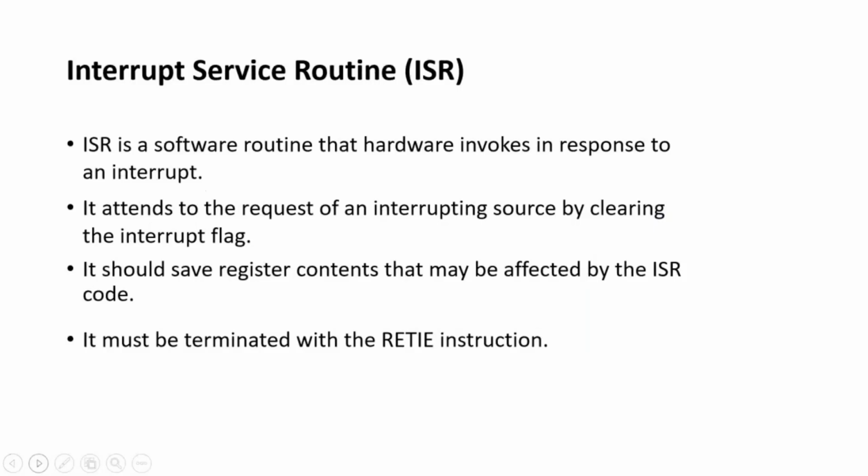Interrupt Service Routine (ISR). ISR is a software routine that hardware invokes in response to an interrupt. It attends to a request of the interrupting source by clearing the interrupt flag. It should save register contents that may be affected by the ISR code. It must be terminated with the RETFIE instruction.